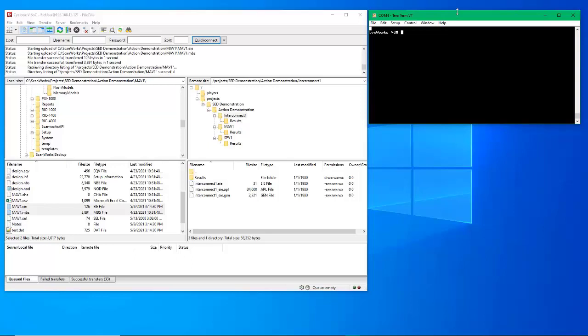So I've established this serial connection, and what I'll be able to do is type commands to run a scan path action, or to run an interconnect action, or to run a memory access verify action. I'll be manually inputting these commands into this window. And again, the tool that I'm using is TeraTerm to have this serial connection into the SoC.